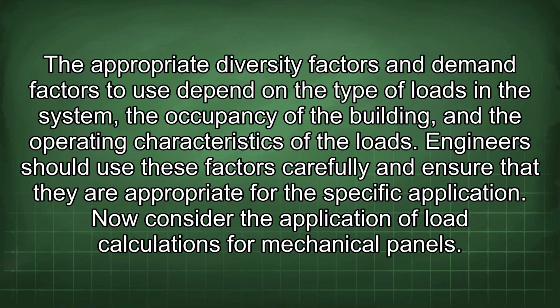The appropriate diversity factors and demand factors to use depend on the type of loads in the system, the occupancy of the building, and the operating characteristics of the loads. Engineers should use these factors carefully and ensure that they are appropriate for the specific application. Now consider the application of load calculations for mechanical panels.